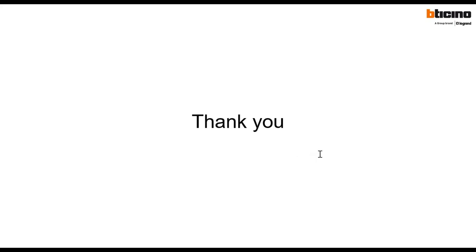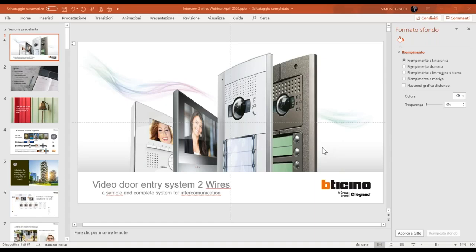Then I see another question. Is it possible to operate electric gates for a garage with, for example, class 100? Is it possible to open gates remotely with a key fob remote directly from the car? Yes, because if you have the connected version, you can use the application to open the door. If it's a garage, you need only to use a dry contact. You have to set up the external panel to give you the dry contact instead of giving the 12 volts for the door lock.